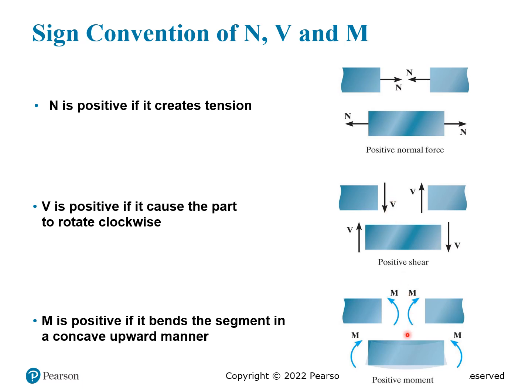The bending moment will be positive when you make this bend upwards. So this is what we define as a positive direction. On the right hand side, this is going to be the positive direction because they tend to make things rotate upwards. So when you make things rotate upwards, that's the direction that is defined as the positive bending moment.